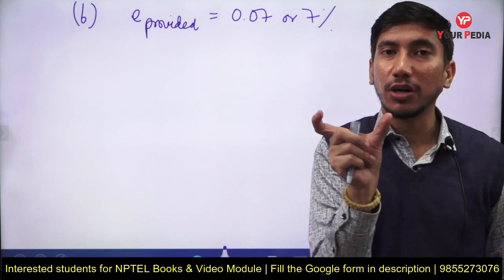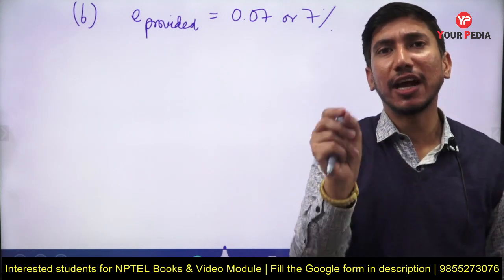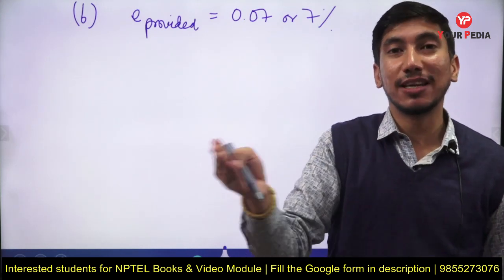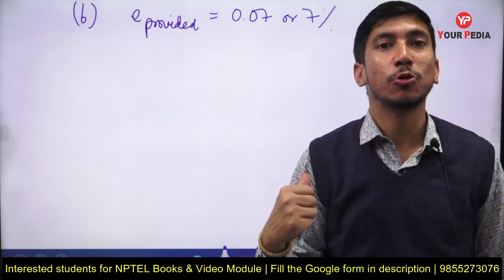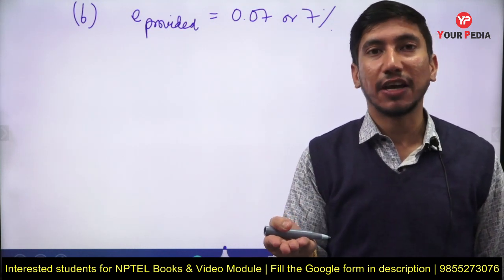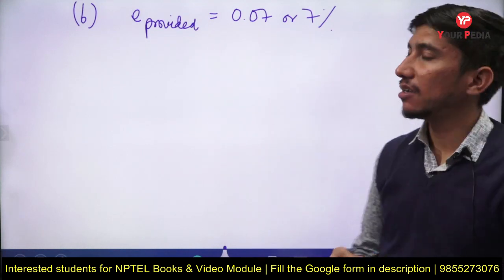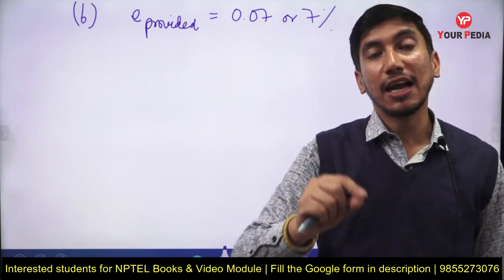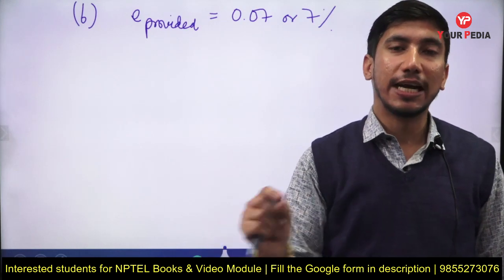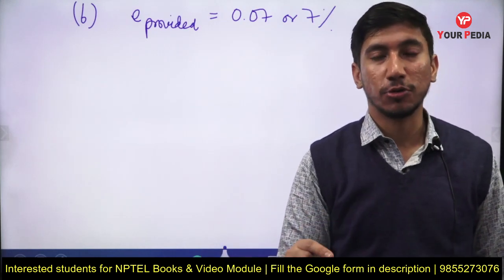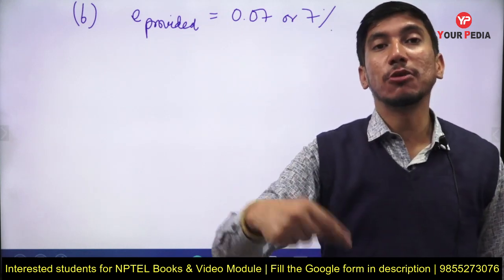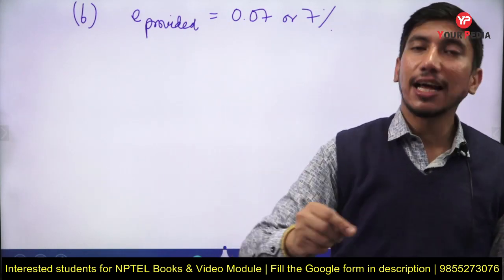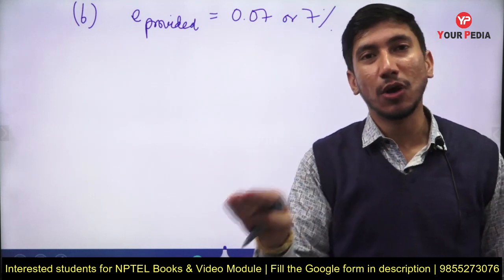So I have to find the required value of F, and if that F value comes out to be less than the safe value of lateral coefficient of friction, which has been given as 0.15, then our design is fine. We can go ahead with this 7% of superelevation and we can still allow a speed of 80 km per hour on our road. But if the required F value comes out to be greater than the safe value, in that case now we have no other choice.